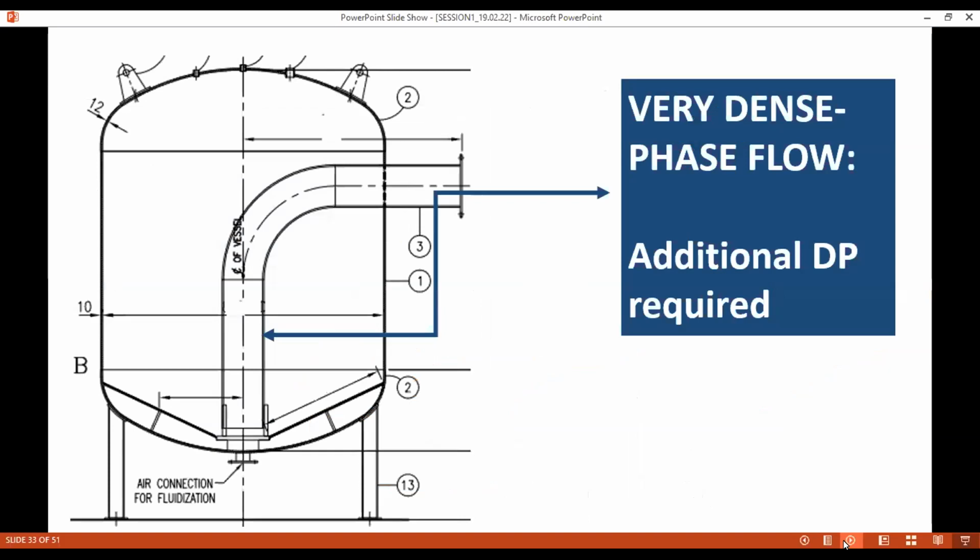In the top discharge blow tank, another problem is that the riser pipe has a very, very dense amount of ash coming through it, because only a limited amount, maybe 30% of total air, goes to the top discharge blow tank via the fluidization pad. So you have 120 tons per hour of ash coming out, or whatever the number is, but only with 30% air.